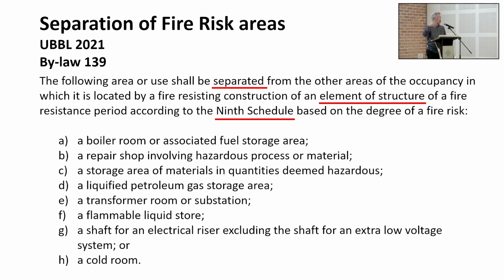By definition, we're just talking about definition. They're not necessarily separating walls, are they? Because you're not exactly separating two different occupancies. They are not an external wall. Maybe they're not an external wall. Some parts of it may be part of an external wall. But really, here we're talking about these walls are really partitions because they don't fall under those specific classifications. But however, Bylaw 139 specifically prescribes if you have partitions making up these usages, then the walls must be constructed with the FRP according to the Ninth Schedule.